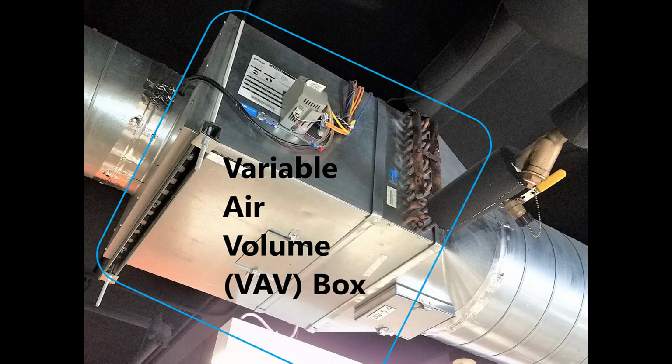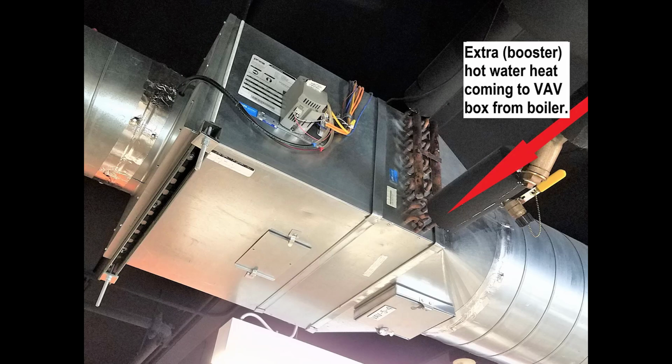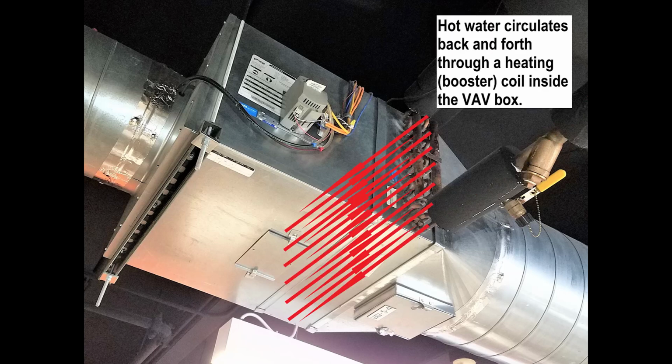The extra hot water from the boiler enters what's called a variable air volume VAV box, which is located real close to the room that needs the extra heat. You might think of a VAV box as a very small air handling unit. Opening the right valve, an actuator permits hot water from the boiler to enter the VAV box. Then the hot water circulates through a heat exchange coil. This is sometimes called a booster coil because it's giving an extra boost of heat, in this case, to already heated air.